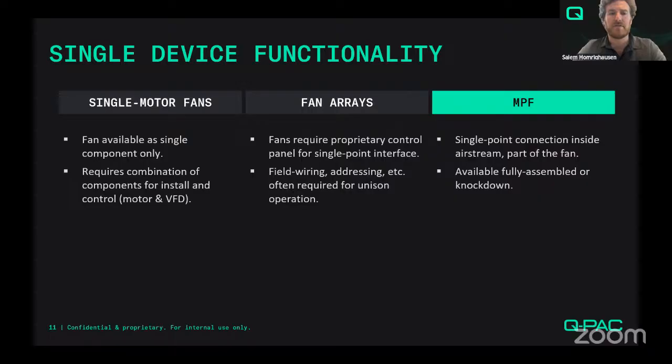Your single motor fans, your traditional blower and AC motor systems. There's a motor, there's an AC induction motor, and there is a blower. When you're maintaining and installing this product, you have to make sure that they are working in sync with each other. So you wouldn't really think of a blower and a motor as a single thing, right?